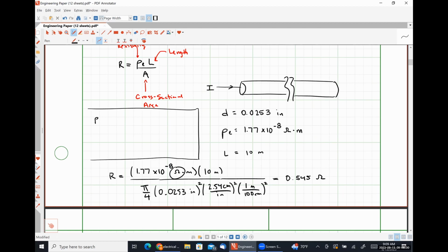So for a resistor, our power is always going to be I times V. And then using Ohm's law, we could express this as V squared over R, or I squared times R. That's just simply substituting Ohm's law into our power relationship. For conductances, it's still going to be I times V, so it's going to look like V squared times G, or I squared over G.